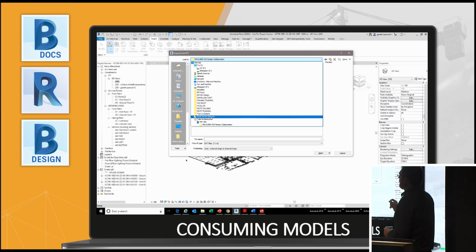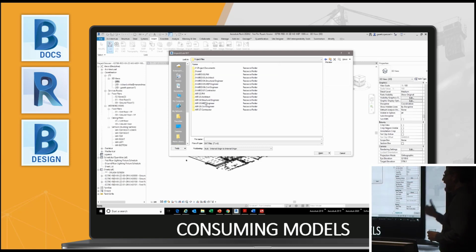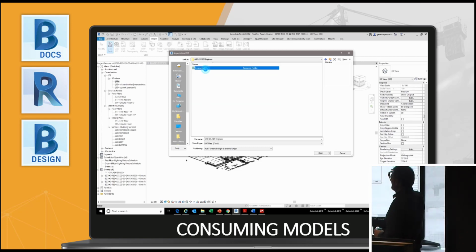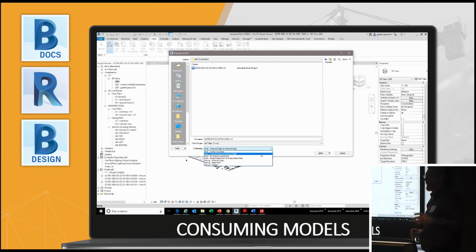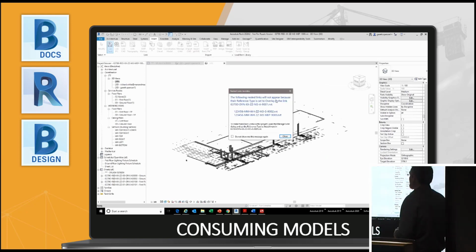Now what we've got to be careful of here, I can see everybody's folders. If I didn't have the admin rights, I would only see the folders that I need, for example, building services, I see building services. I'm going to the building services folder, under consume, select the architecture file which I want to load in, I'm going to select it and open it up. And load it in. Now obviously, I was talking about insertion points earlier, make sure you check your insertion points.